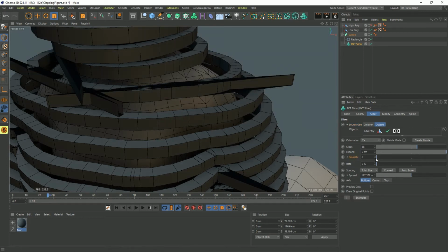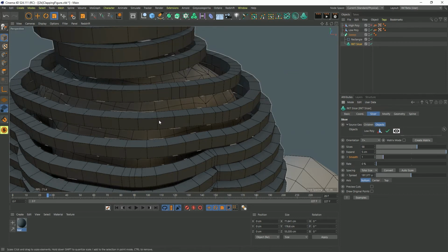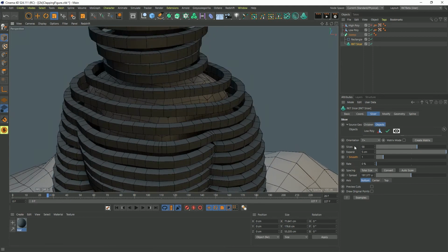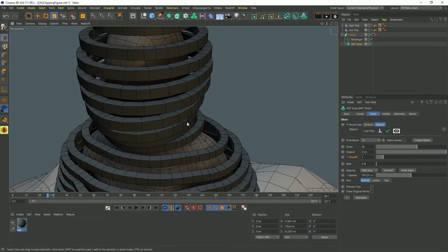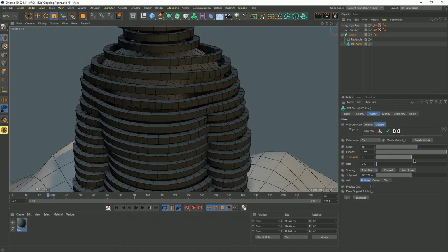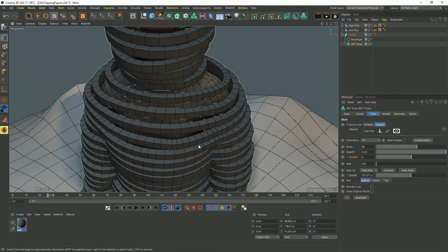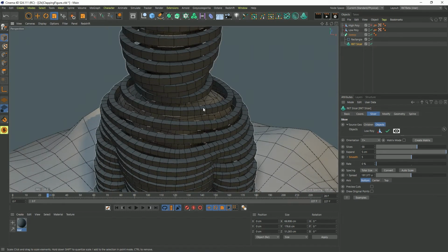By grabbing smooth and increasing it, let's say 1, I've done 1 iteration of smoothing. So what it's doing is taking 1 point and checking on its two neighbors and going to the average point between them. And it's going to keep on repeating that iteration. So even by doing one iteration of smooth, it's able to calm down those kind of overlapping edges and make cleaner geometry. So that's very, very powerful. We could add additional iterations to it and smooth it out more. And you just want to make it so that the splines are happy and something like the sweep or the extrude would work with it. We'll get into the specifics of that when it's time, but you can see how those combine really well.